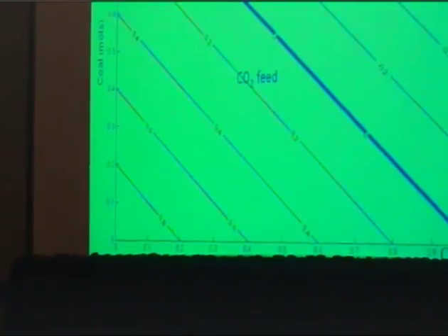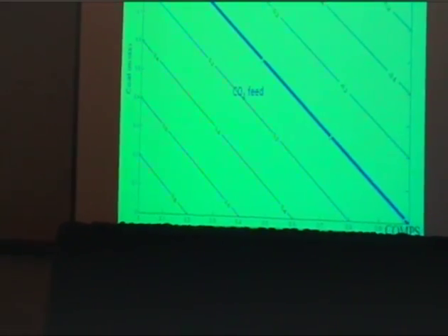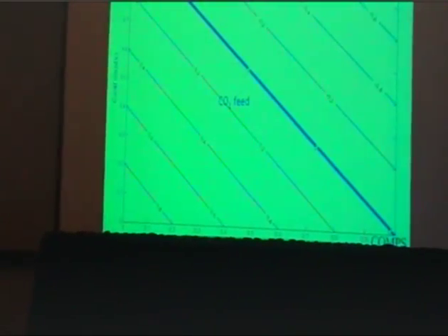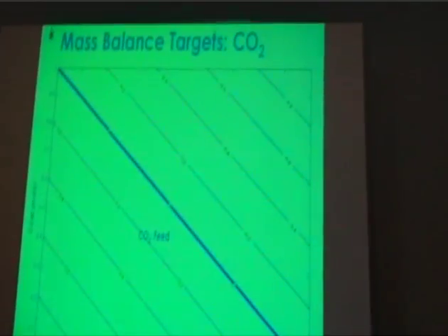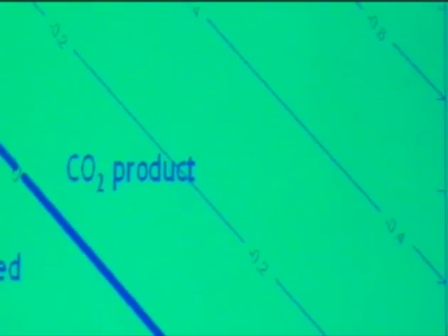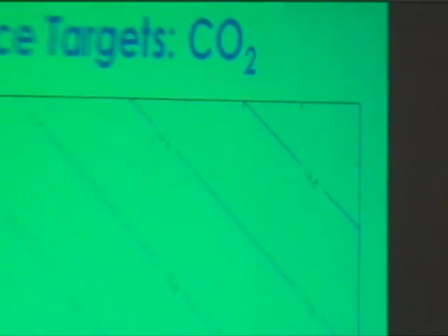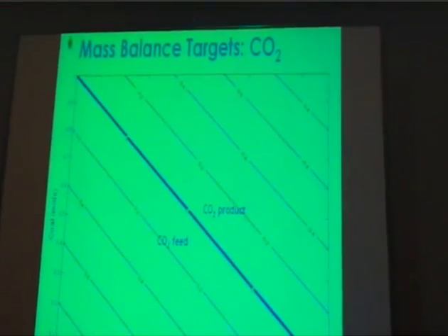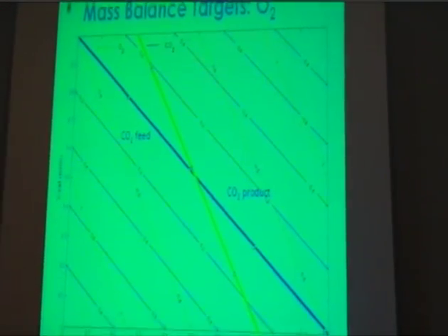The technology to actually implement this is not what we're stating. We're merely stating that using a feedstock of those 2 combinations to produce 1 mole split in various ratios between the CH2s and the methane would allow you to actually consume CO2. On the other hand, if we were operating above this curve, we'd actually make CO2 as one of the products. Right? And this is working again from a fundamental perspective. Now, no one, I think, in the room would ever think of using CTL in a process that actually consumes CO2, which is why we're looking at sequestration.